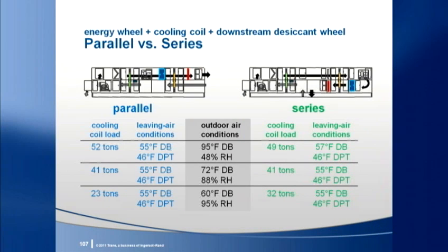As it was for the units with a single recovery device, deciding whether to use a parallel or a series configuration is not always clear. The series arrangement will save more cooling tons on the hottest design day and during the warm weather. The parallel arrangement will save more tons on cooler days when it's still humid enough to require dehumidification.